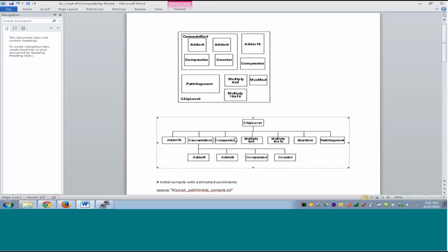He will assign input and output delays which are slightly more aggressive in nature for this block. Plus, the designer has to make sure that inputs and outputs are registered. If the inputs and outputs are registered, it is very easy to work out the input output delays. There will never be an issue at this point. So every block has its own constraints, and every block will go through synthesis.